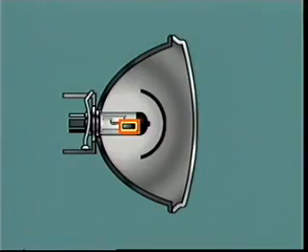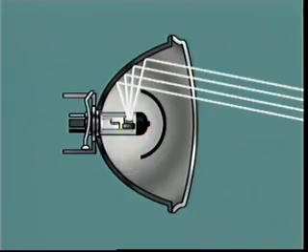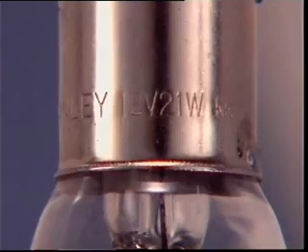Some headlight bulbs have a partial shield below the dip filament. This shield stops light from the filament striking the lower part of the reflector. The shield provides the primary shape of the dip beam. The final shaping of the beam is carried out by small cylindrical shaped prisms in the headlight lens. This provides a dipped beam that is asymmetrical.